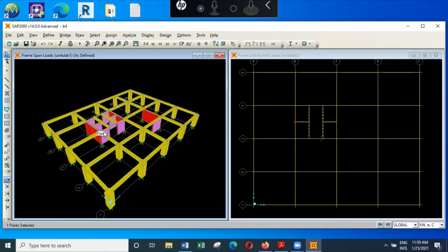So I'll show you later how to add more mass onto the structure. And if you want, you can actually select a point and allocate a mass. On the other hand, you can ask the program to derive the additional masses from the loading that you have specified. And we'll make use of that particular method. But I'll show you why we need to adjust the mass.